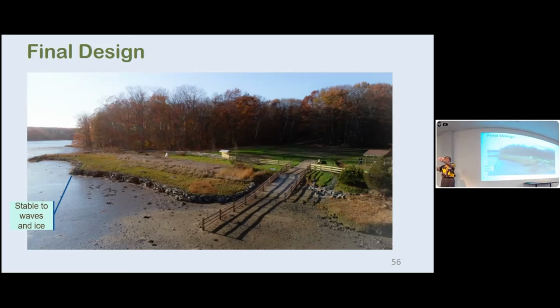And then we sort of step in the middle of that and we disrupt it. Sometimes the disruption's so small, it doesn't cause a problem. Other cases, if you look along the New England coast from Long Island up to Massachusetts, you put in breakwaters to stop the erosion. That disrupts the littoral cell of sediment and it just moves the erosion somewhere else where you don't have breakwaters. And we successively just put in more and more breakwaters because we chase the problem.